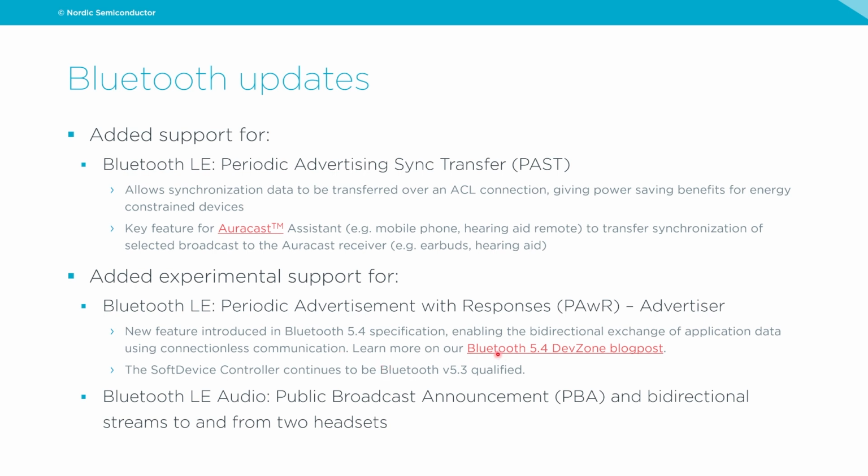We have written a DevZone blog about Bluetooth 5.4, which includes a description of periodic advertisement with responses. So if this is something you're interested in, I recommend that you go and read that blog post. It's important to point out that the SoftDevice Controller is still Bluetooth 5.4 qualified. And we also have, on Bluetooth LE Audio, experimental support for public broadcast announcement and bidirectional streams to and from two headsets.